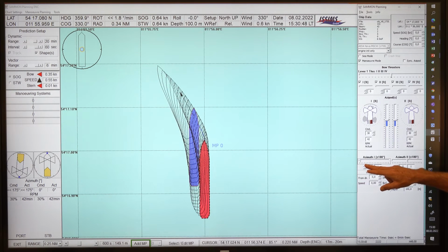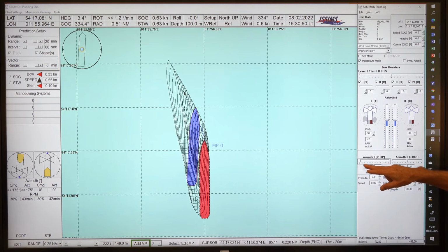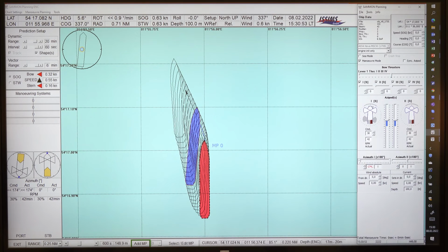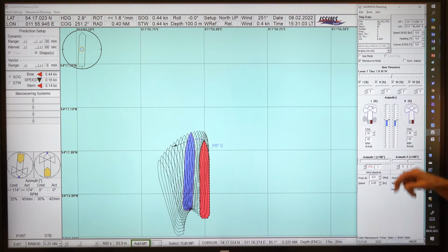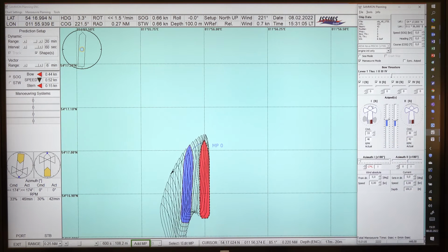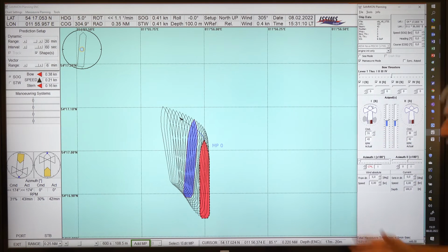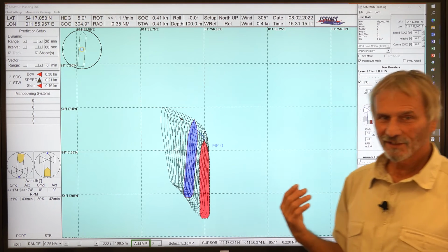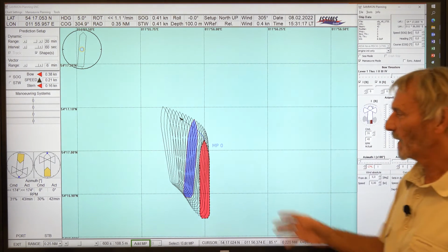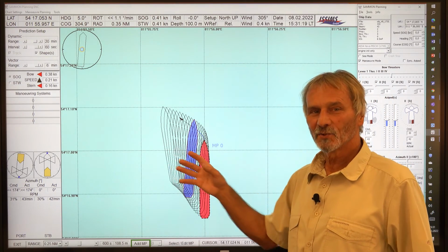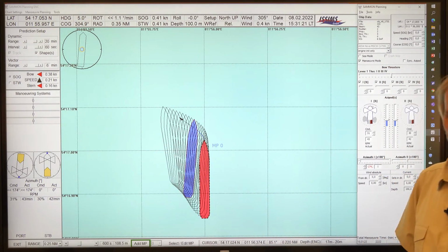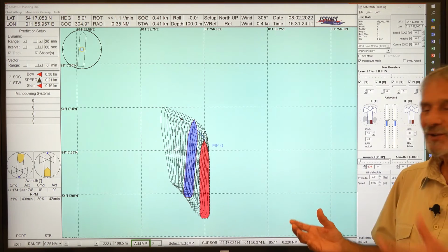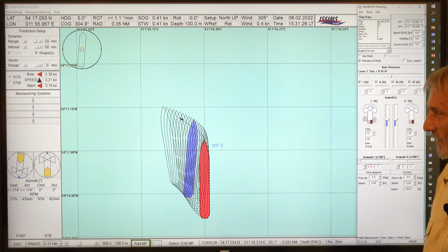So you can adjust it in a way that you go 10 degrees, for instance. So we can really use the ship for crabbing, sideways crabbing. If we also adjust a little bit the forward direction, then you see that you can really adjust and move the ship in any direction you want. So just in case your bow thrusters are out of order, then you might also try crabbing with the ship with this toe-in configuration.